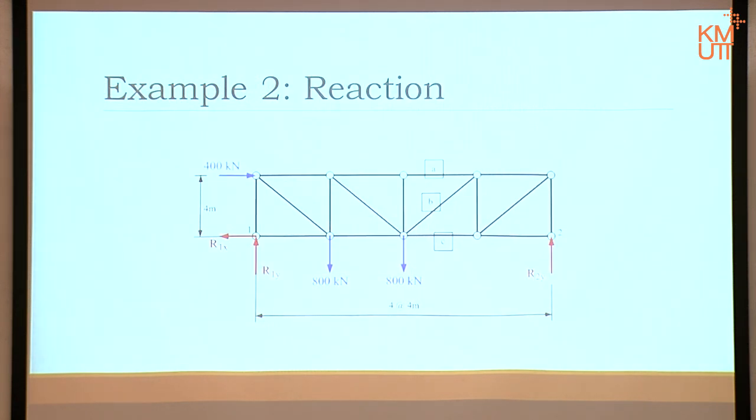Now, before we actually start analyzing it, from this point onwards, I'd like you to consider your objective for a little bit. Now, the word section method means I will cut it through here. Notice that there is not a point anymore, it's the whole body now. Correct? So I still have sigma Fx, sigma Fy, sigma moment. Right? Now, if I cut this picture here, then I can look at the right hand side, my choice, right?